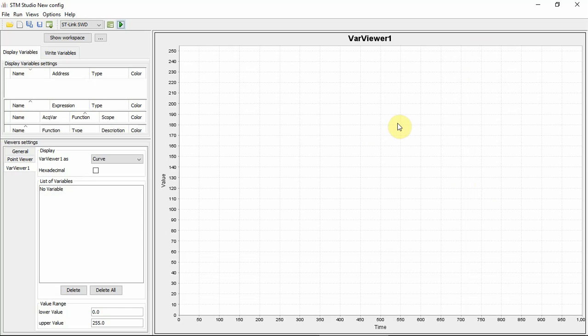First of all, we'll need to build an application. The application I'm going to use in order to see all the features is reading ADC. And since the ADC needs some kind of waveform, we'll use the DAC, the internal DAC of the STM32, in order to create a waveform. So from one pin we'll create a waveform, and from the other pin we'll read it.